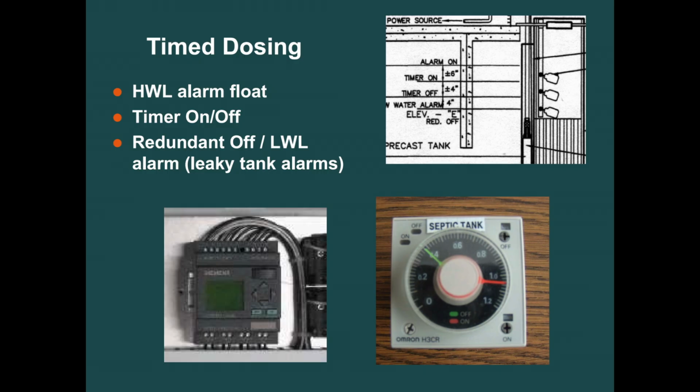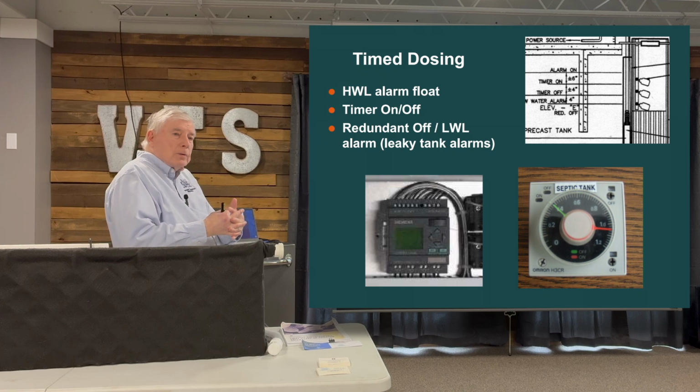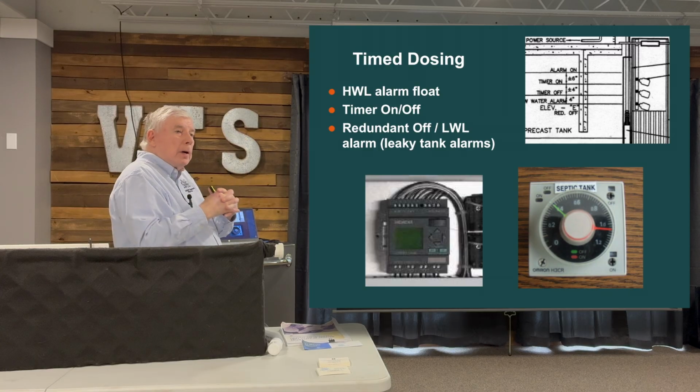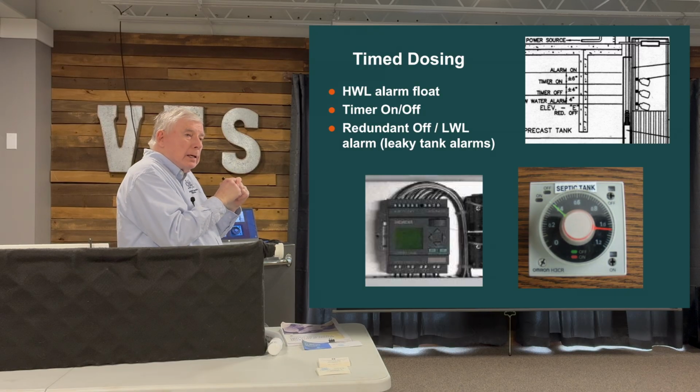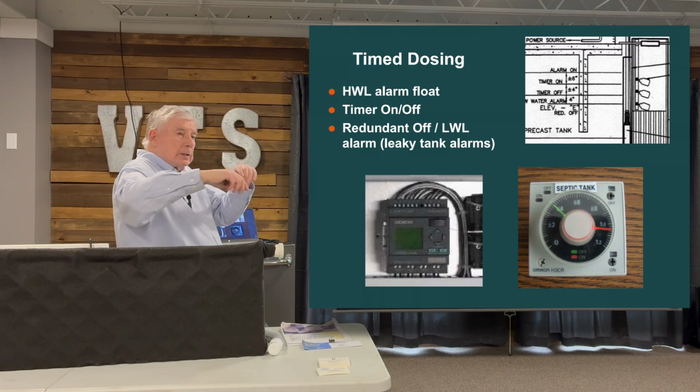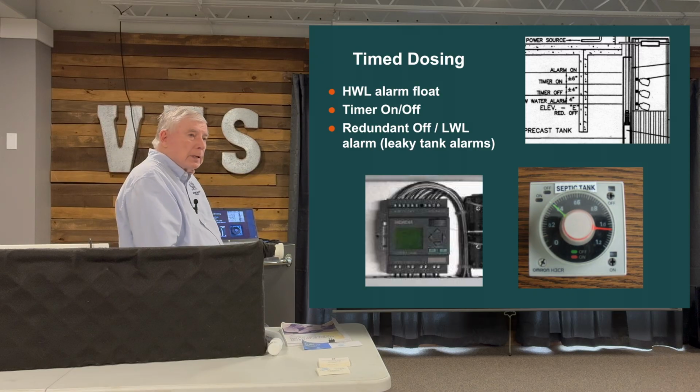Time dosing is one option, and we've got these older timers, but you set the pump run time. You use a pump, number one, to dose them, and then you use time dosing to control the amount of time the pump operates. So typical setting on these in our mound systems and my designs has been 1 minute every hour. So every hour the pump kicks on for a minute, and it fills the pipe in the dosing field, and then that pipe drains out. You know, it cuts off. So 60 seconds out of every hour. So we use time dosing to do that.